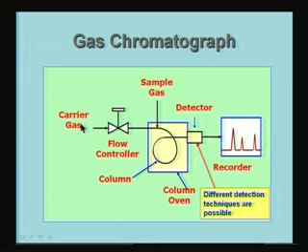That means the carrier gas has some property, and the sample gas must have the same property, but a slightly different magnitude. I will refer to this a little while from now. The detector will now sense the presence of different species, and if you record the species coming out, first the lightest gas, then a little heavier gas, and so on will come here.